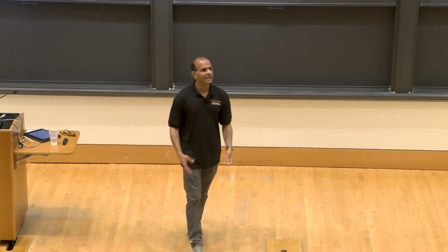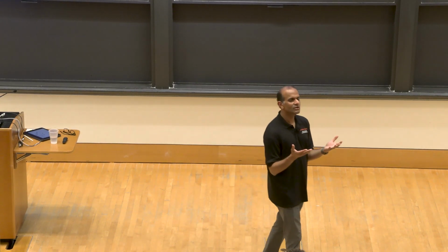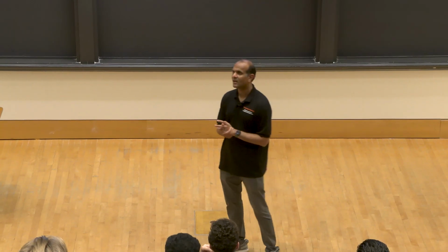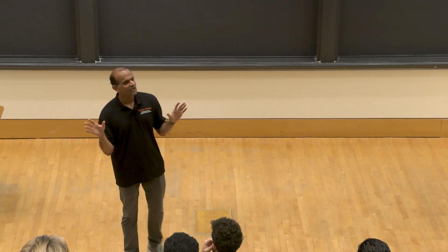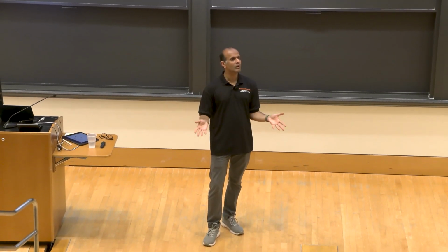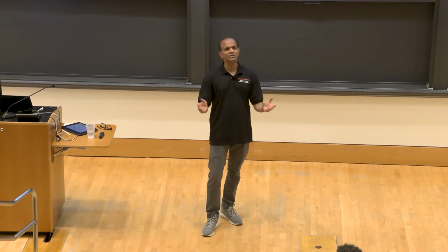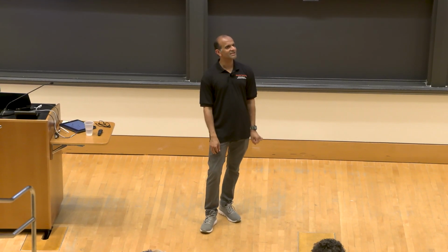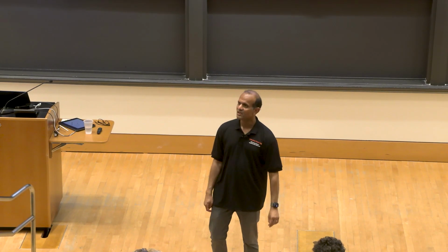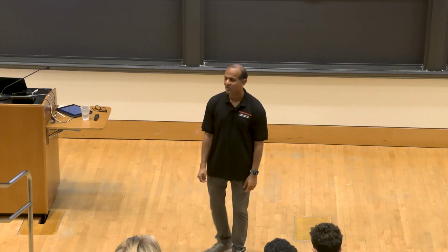You take the solution, and from it you can figure out what those model coefficients have to be, okay? So you don't have to tune anything. You just set the mesh, specify the boundary conditions, and run it, and you get what you get. If you don't like what you get, then so be it. That's it, yeah? Which is very different from the RANS approaches. So it's good to know how we do this.